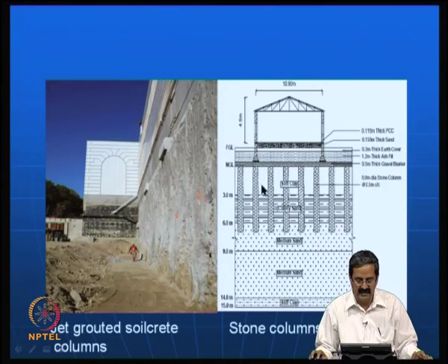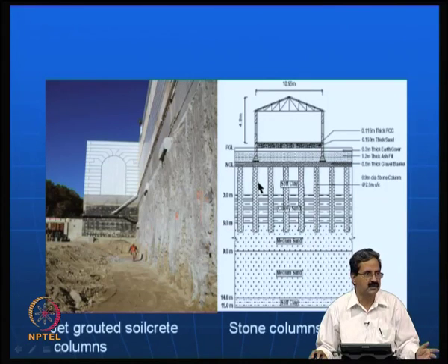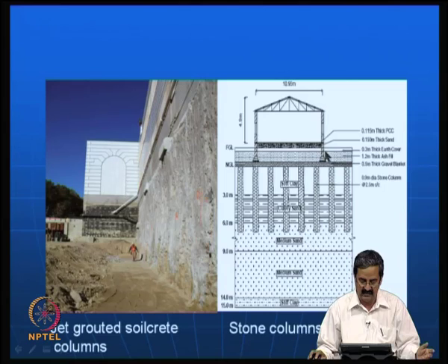Previously there is a soft soil here where the bearing capacity is very low, say maybe 5 ton per meter square, a very low value. But if you put in all these stone columns, and you have a gravel blanket, you may even put geotextiles or geogrids, then you can put the structure, otherwise it becomes very difficult. So, stone columns are very convenient in many structures.